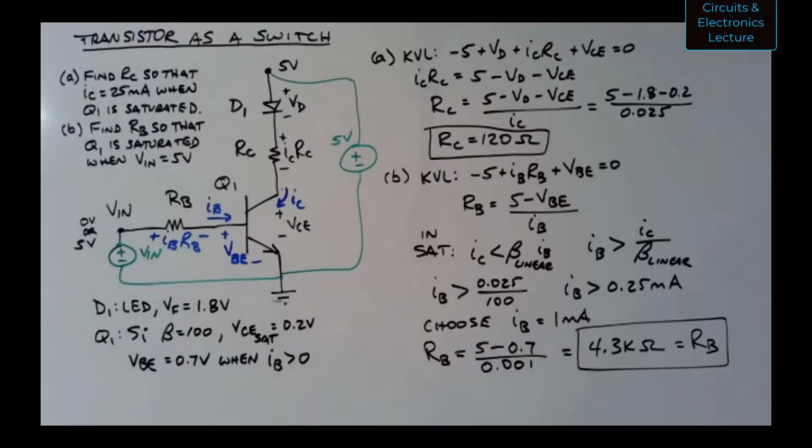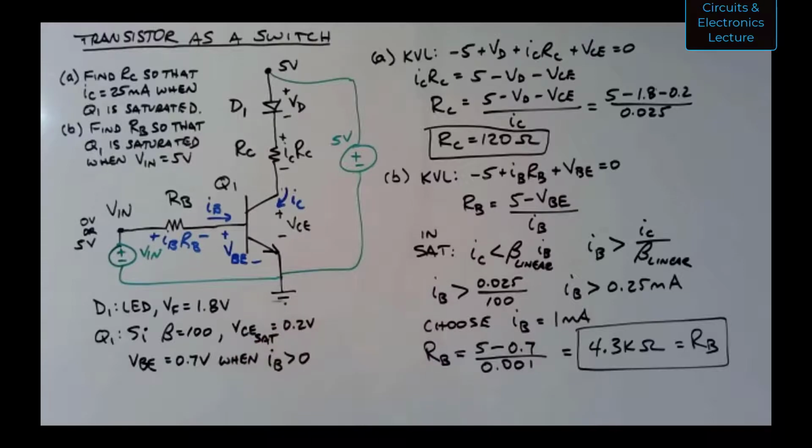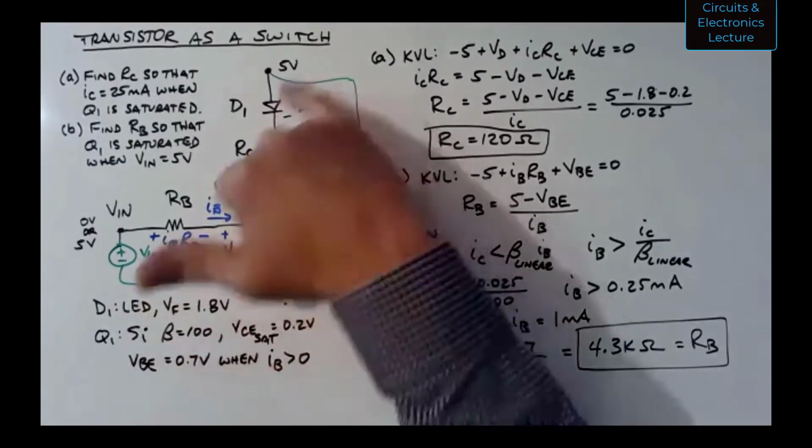If the problem says the transistor is saturated, you can assume that VCE is 0.2 volts. If it says the transistor is not saturated, then you don't know VCE until you figure out the current IC and then do a KVL. I'm just asking, we're given a scenario where the current flowing through RB is greater than the one found, so that's basically the choosing phase done for us, right?